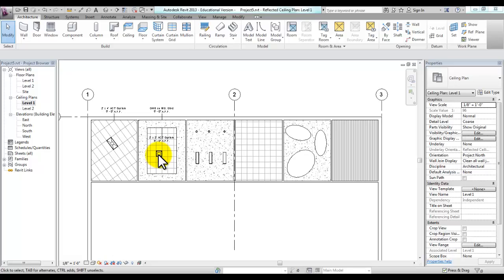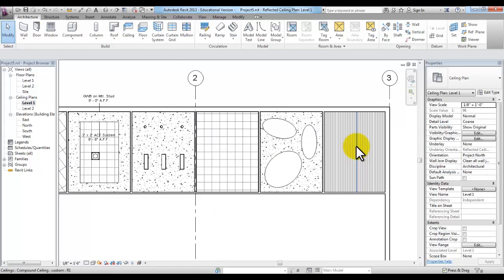Some lights are created to snap to the grid and others to be placed on the face. Sometimes we can open up those families and change them so that they can snap to the grid. So do the best you can to get these close to the grid, and then you can rotate your fixture into place and establish here different ceiling layouts based on sketching and changing material.